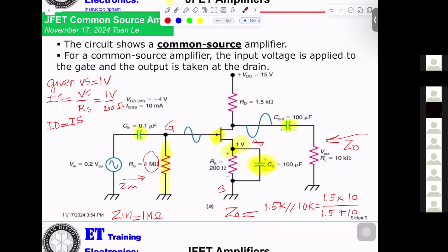But the reason is, why do we need to connect the bypass capacitor? Because you don't want the DC involved. That's what it's bypassing. It's bypassing RS, the source. Because you want a clean AC signal? That was a good try. Yeah, I like that a lot.